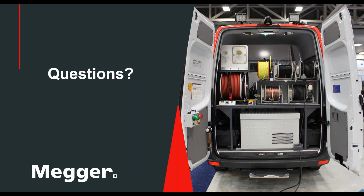From a practical point of view, probably not at all. You got to remember, many times when you're fault locating, you are working on an aged cable, and you do not want to thump it at any higher voltage or any longer than you have to. But the thumper itself didn't create that damage on that old worn out cable. It was already there.